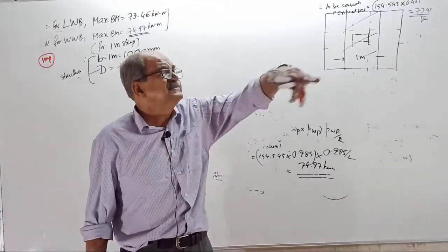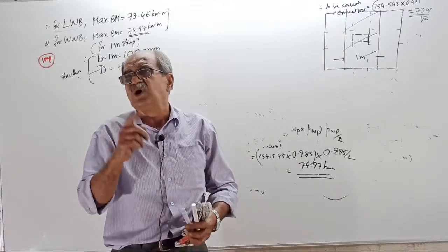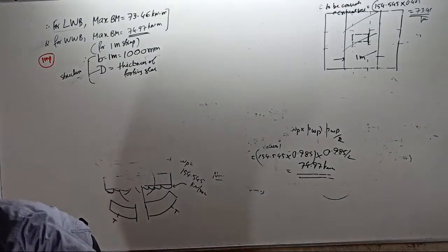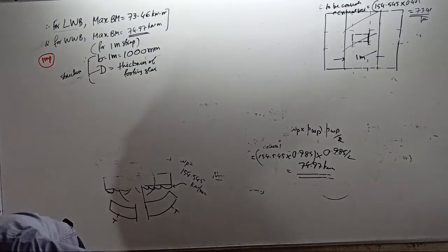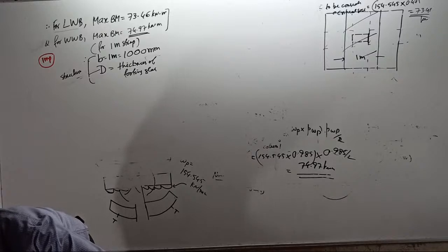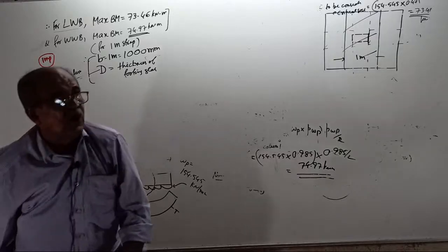But for a footing slab, remember, slab thickness is to be finalized based on bending or shear? I am asking, bending or shear. This I told you: for a foundation slab, it is always based on shear.